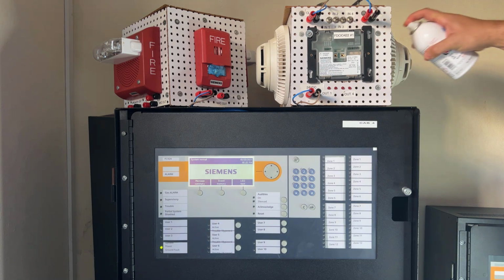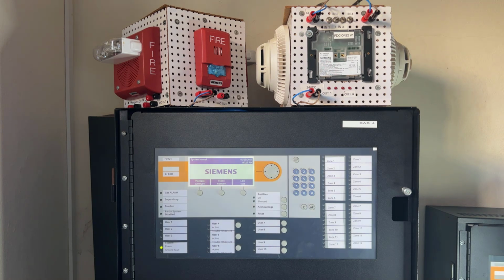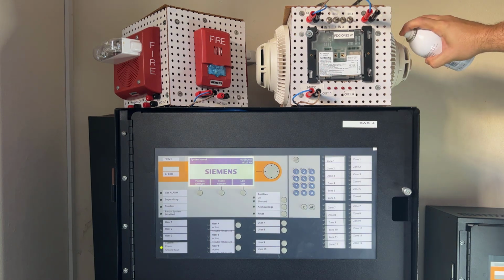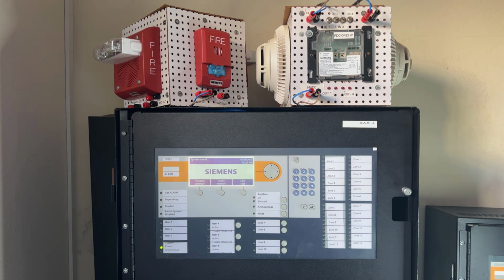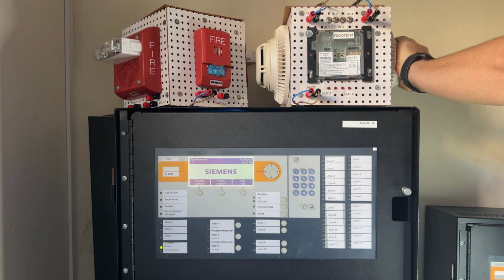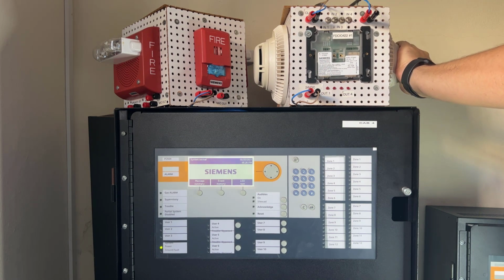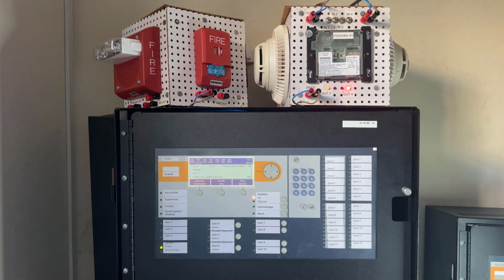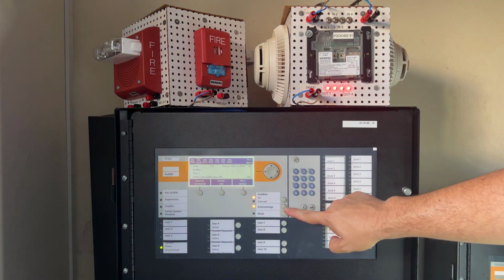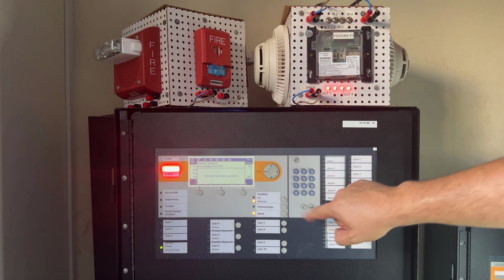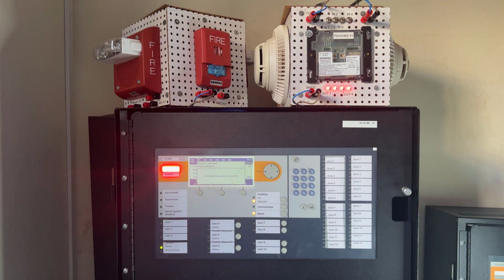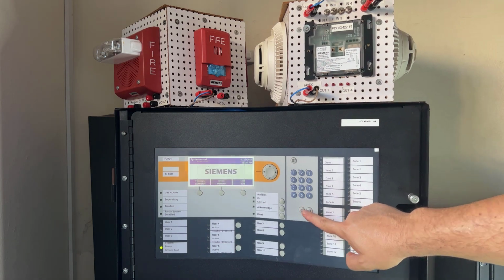Let me show you an example. You have seen the amount of smoke and time that it took me to test the detector in the different test modes. Now, without changing the detector's original sensitivity settings, which is set to robust, look at the time and amount of smoke required to activate my detector. It takes considerably more time and smoke. Imagine these extra resources multiplied by the number of detectors on your site.